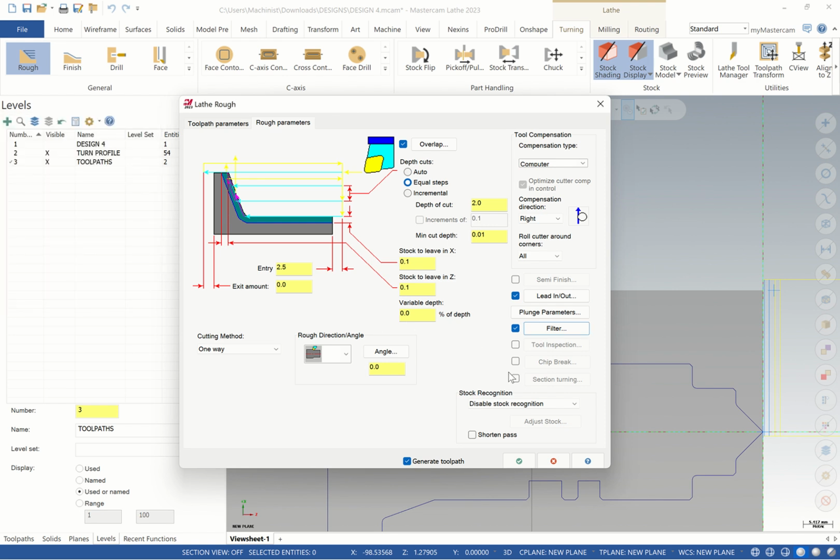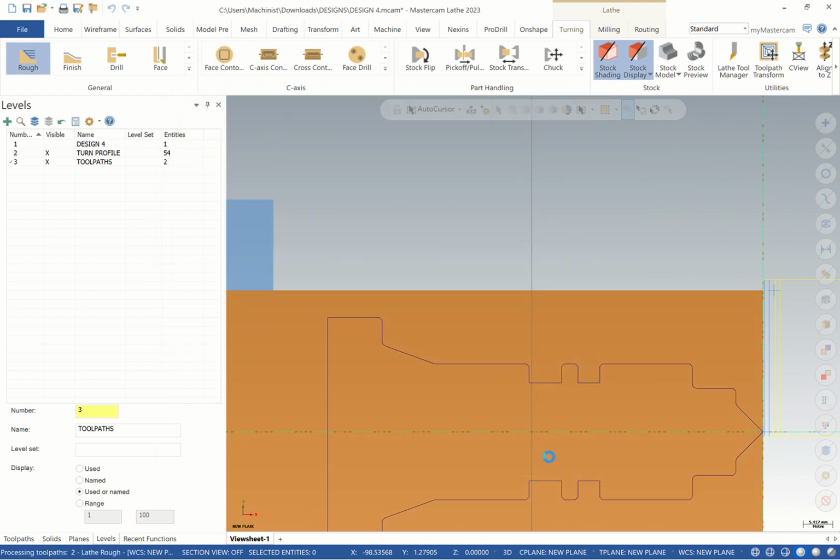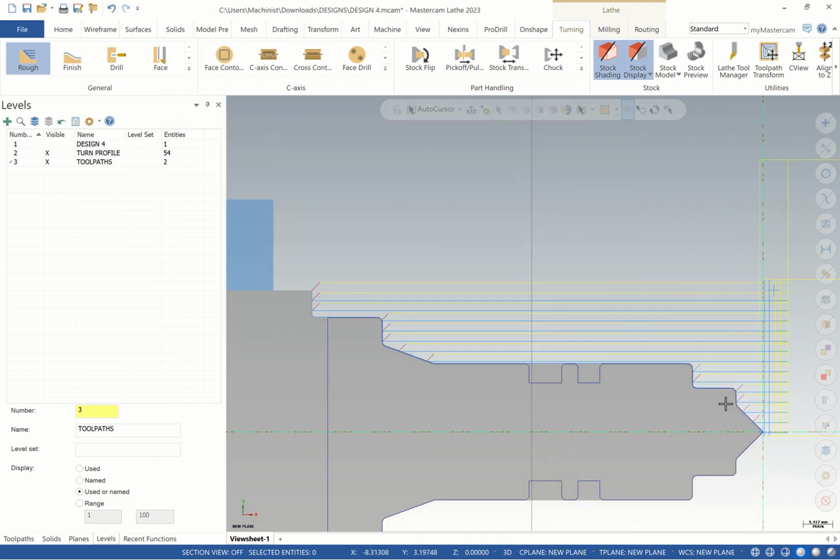Okay. I want to show that I use the stock boundary for the purpose of calculating the parameters for cutting, so that I'm able to know where my workpiece is and how it is. So I can also shorten the toolpaths and say calculate. It generates the toolpaths. The beauty with this one, you see, I have done what we call lead out. I have extended by 3 millimeters.